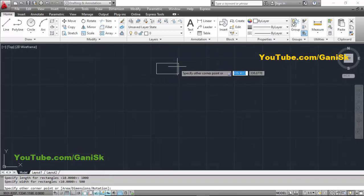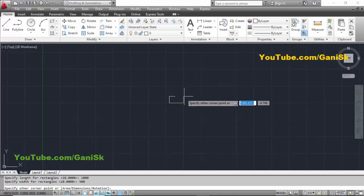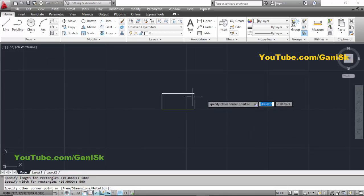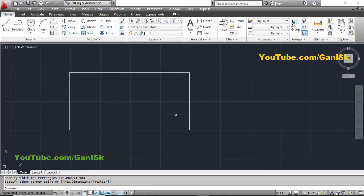You can see now we have the rectangle with length 1000 and width 500, but still the rectangle is not placed. We need to specify the side of this rectangle, so click on the screen to place the rectangle. Now we have the rectangle.